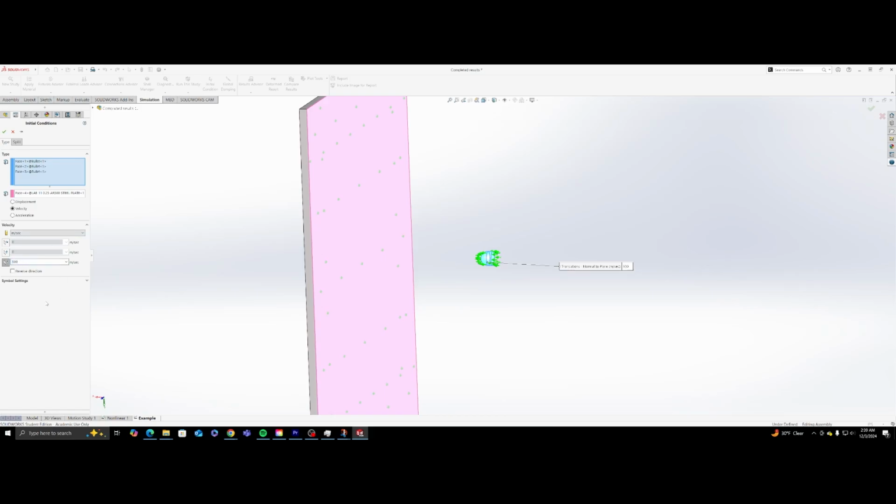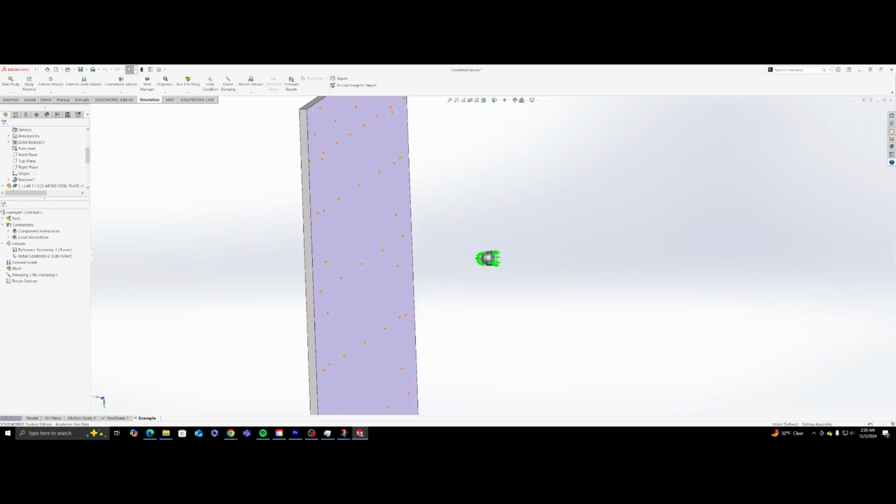You may be asking yourself if that seems quite low for a bullet, and yes it is. One of the many problems with Solidworks is that it cannot do over certain speeds, and if this bullet deforms enough and destroys the whole mesh, the simulation will fail. Important to note that. So, once we've done that, we're going to want to create our mesh.